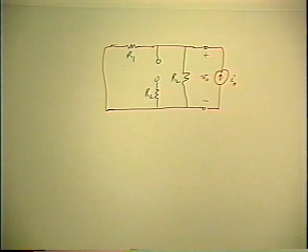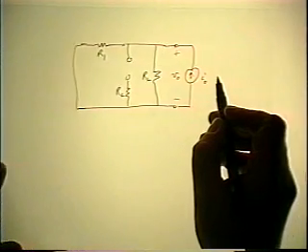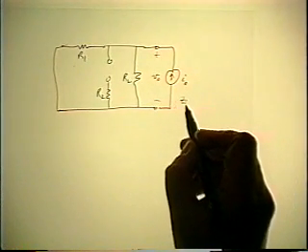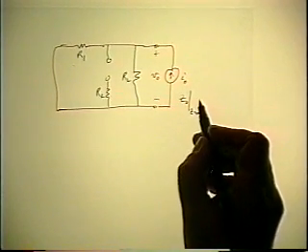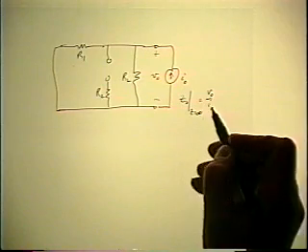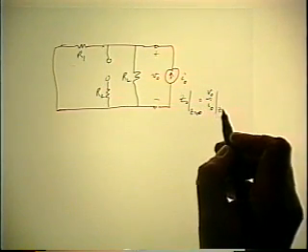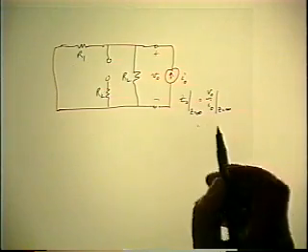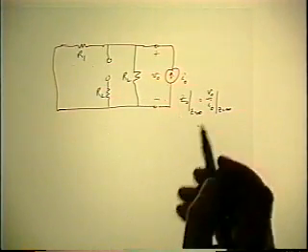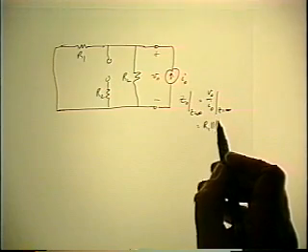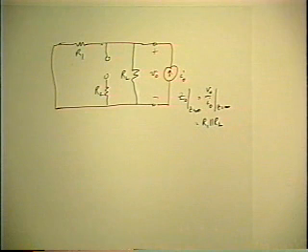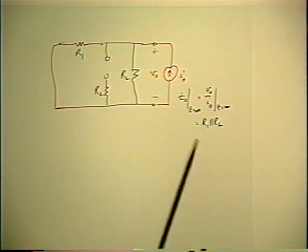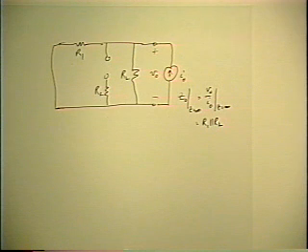So the output resistance, say Z_O with Z infinite, is V_O over I_O, which is R1 parallel R_L from that model. So that's the reference circuit and the reference value of the output resistance.